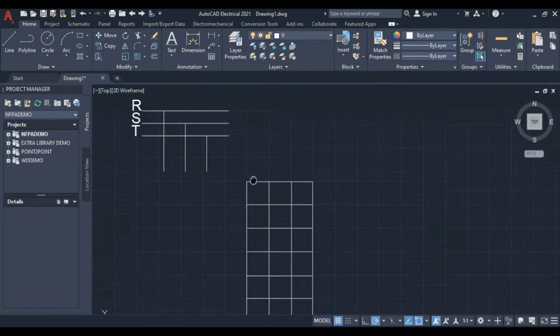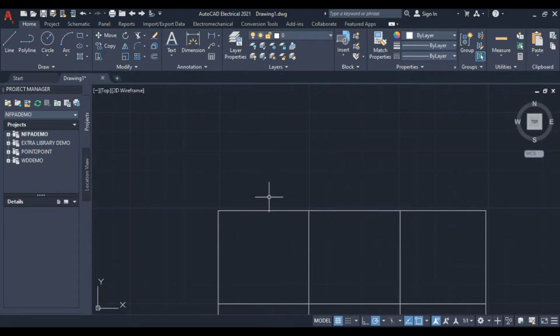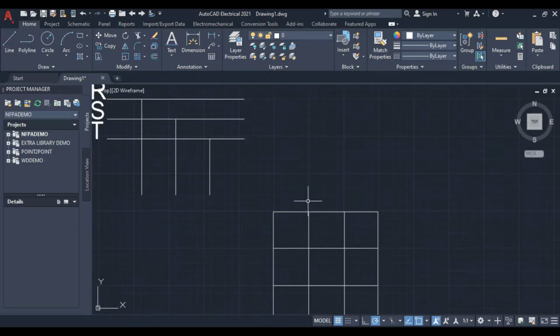24 parts, 24 cubes, and you can draw a triangle here and a Y in here to indicate that it's a Y and delta connection at the end of your three-phase motor, and you can write 1 and 0, and I will explain why. In our last circuit we had 0 here, 1 here and 2 here, but here we have 0 here, star here, delta here, and we don't call this Y. We call it star. This is the delta connection, delta.